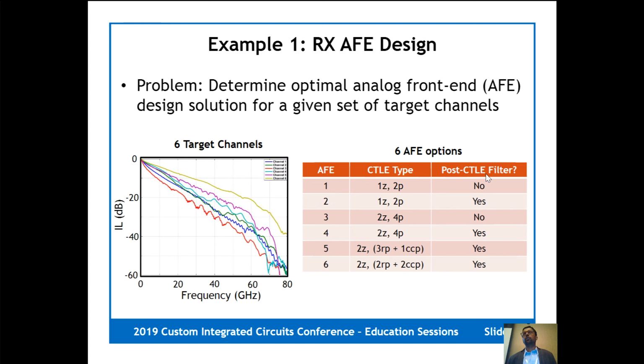All this is doing is filtering out noise. There's only so much noise filtering you get with the CTLE, and this one cuts off the frequency a little more. For the most part, it comes for free from the multi-stage VGA that follows it. But this was just to see how important that is.